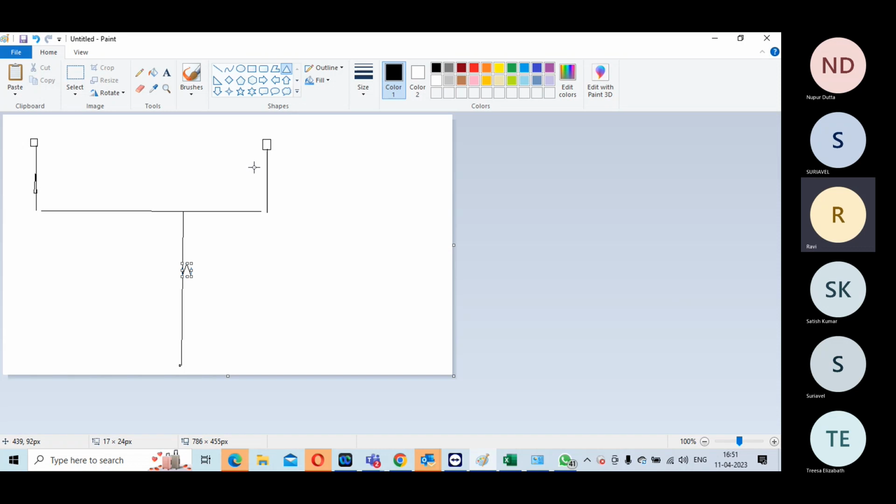So how do you do it at what stage? Don't touch registers. You can fix timing by only moving the data path cells, non-sequential. You have an option like that. You go and upsize only non-sequential cells. You can try these options.